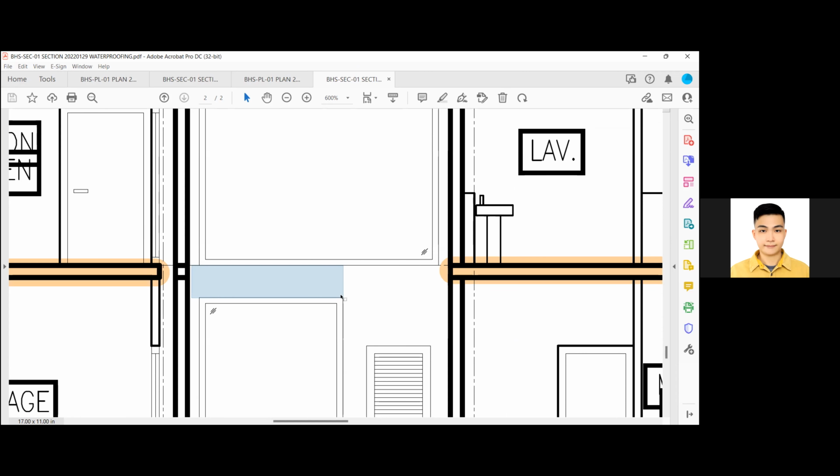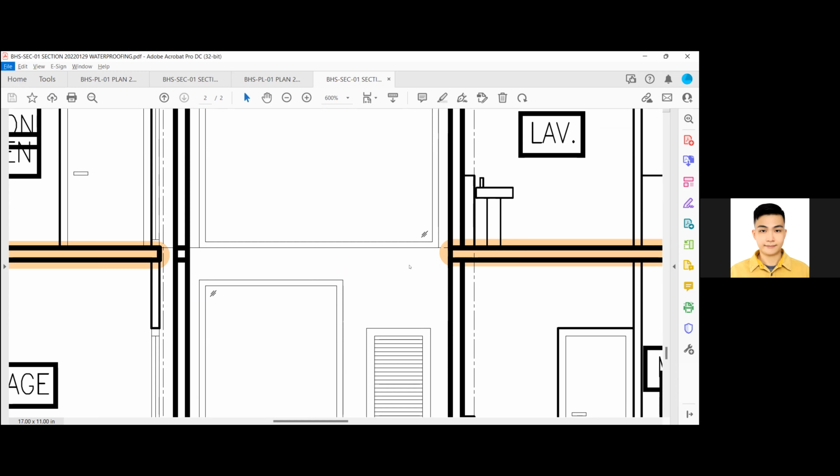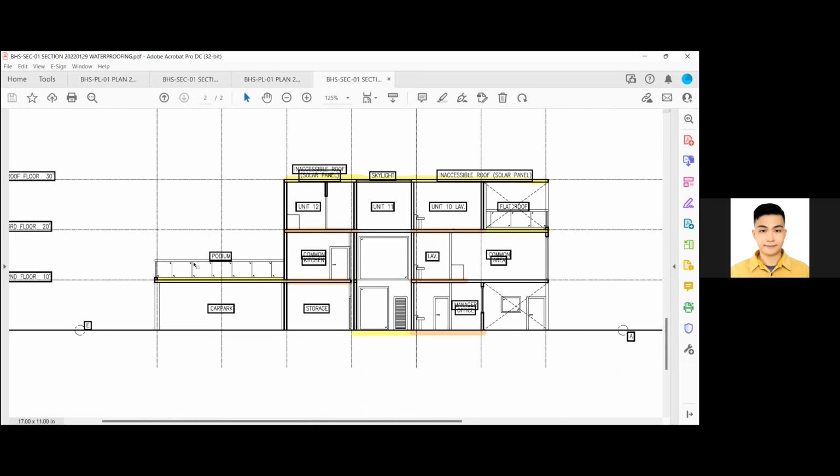So for your case, thickening the floor slabs to 1 foot should be able to adapt to all scenarios. For the inner floors, yes, but for the podium, I think 4 inches should be enough, like 4 to 6 inches, because it's possibly going to be a composite steel deck.